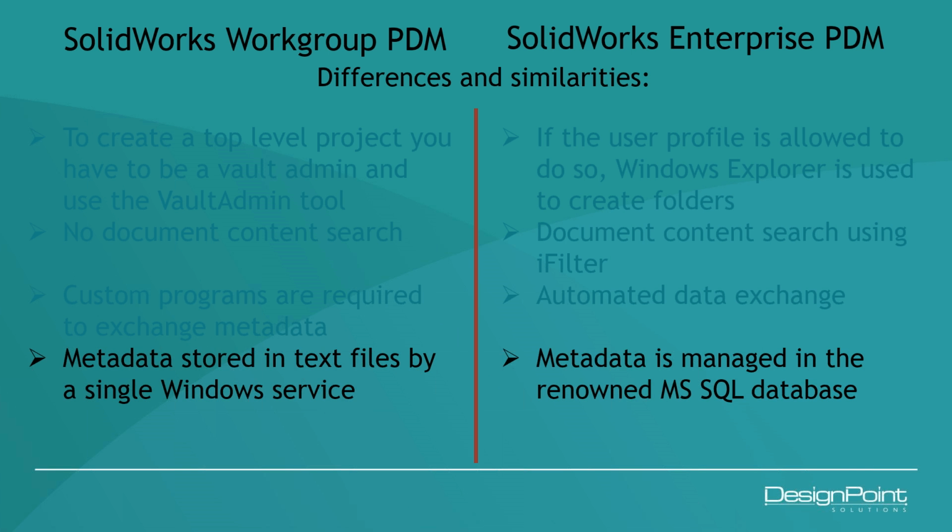For Workgroup PDM, metadata is stored in a text file, and it's managed by a Windows service. With Enterprise PDM, the metadata is managed in a Microsoft SQL database. A lot of people may not be aware of this, but SQL is included when you purchase EPDM. It's not a free or stripped-down version, it's a SQL Standard edition. You can use it only for EPDM, and you can use it to retrieve your information.